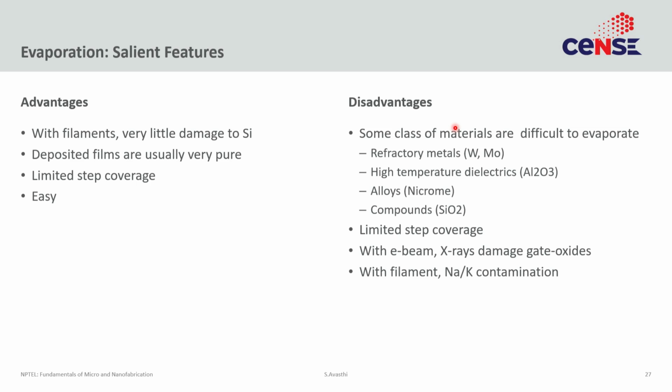Okay. You would think that, oh, you are heating up, you are melting up, so the atoms that are raising would cause some damage. No, if you actually measure it, it is very gentle. It is a very gentle deposition. So, it can be done on very soft films. What are the disadvantages? You can't do it on refractory elements. You can't do it for dielectrics that are high temperature.